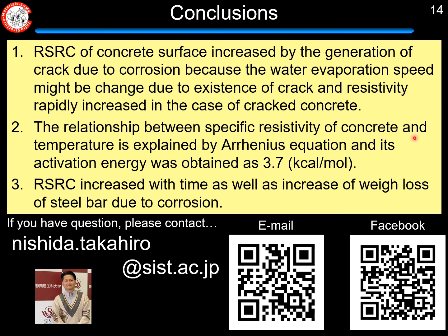Second, the relationship between specific resistivity of concrete and temperature is explained by the Arrhenius equation, and its activation energy was obtained as 3.7 kilocalories per mole. Third, RSRC increased with time as well as with the increase of weight loss of the steel bar due to corrosion.